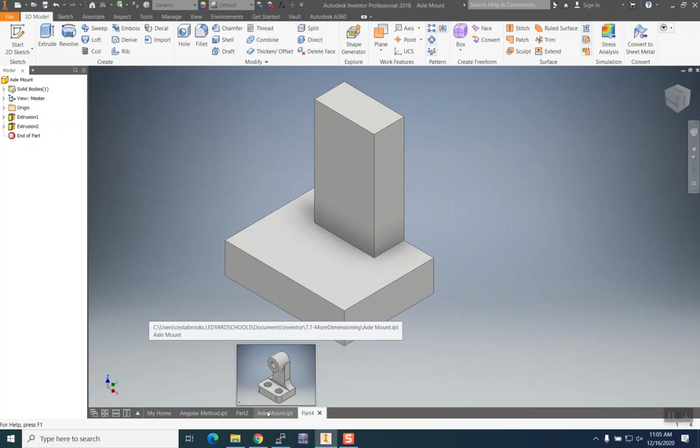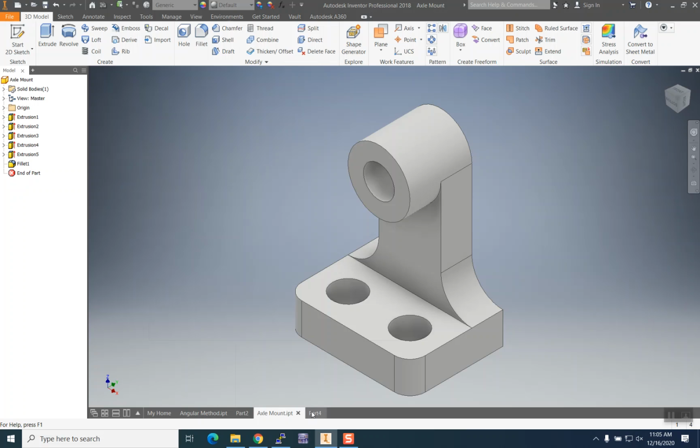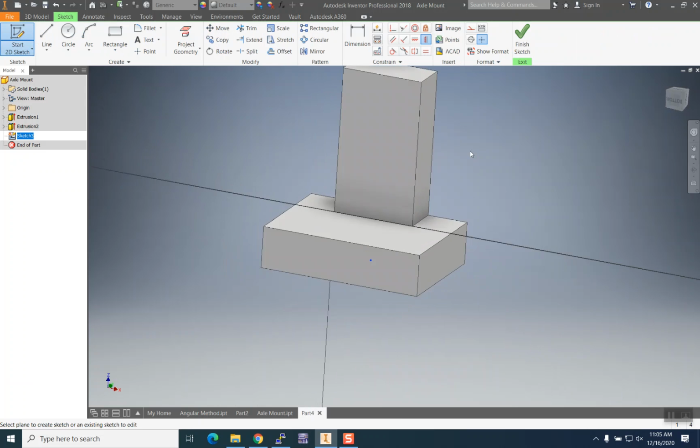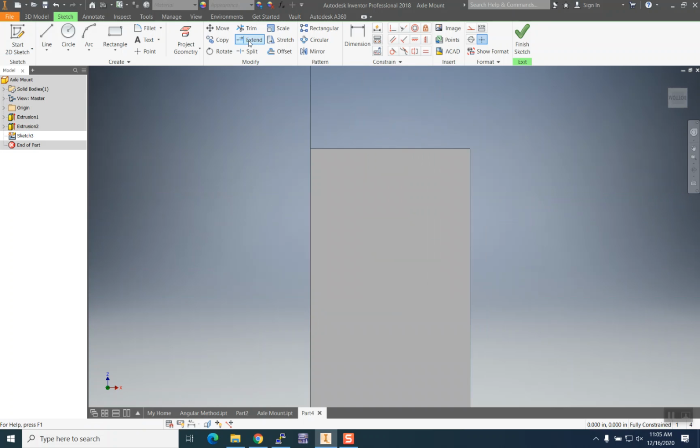The next thing we want to do is that cylinder in the top. We'll take care of those holes later. So to model the cylinder, start with the sketch on the surface of the pedestal. And now this is again where you need to carefully watch your cues. Choose a circle tool. Make sure you snap to the midpoint of that line. You can see my cursor, the little green dot there. That's where I want to click.